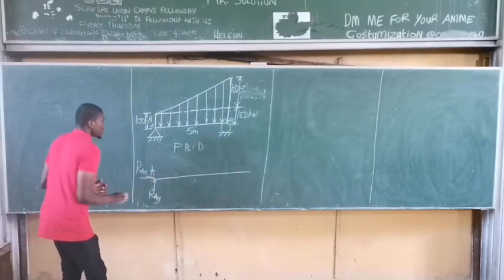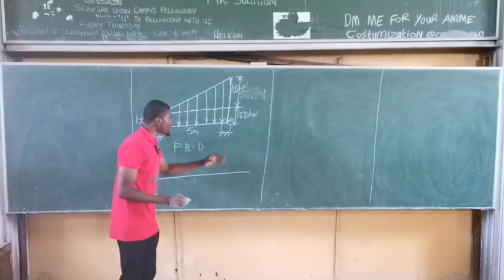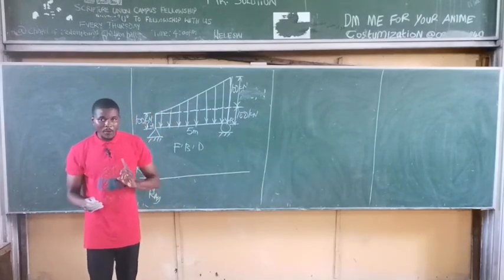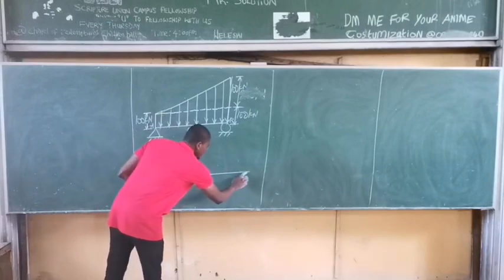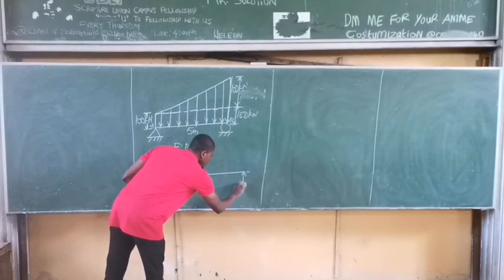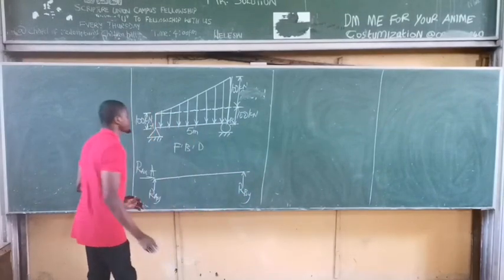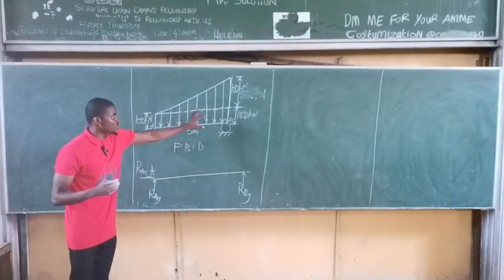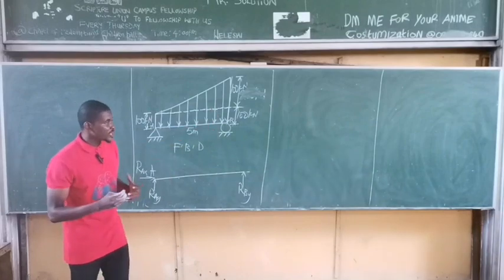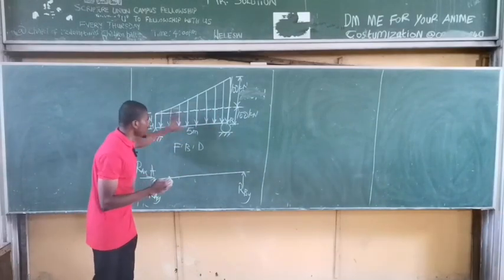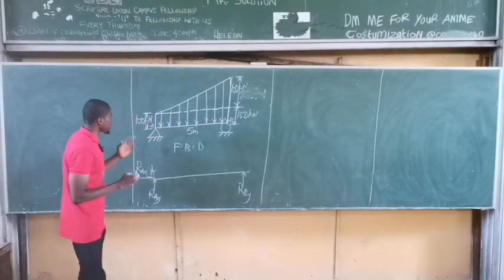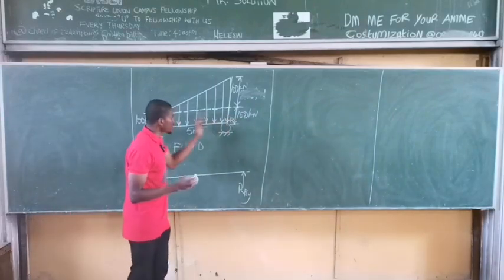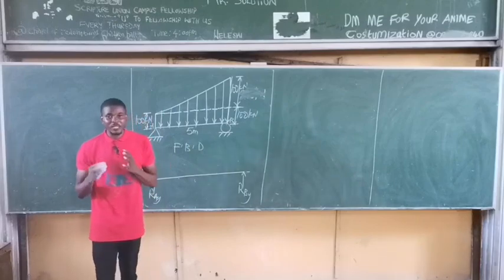This is point A. At point B, we have a roller support, and for a roller support, we have just one reaction, normal to the surface. So you indicate just one reaction, RBY. Now, the problem is how do we then convert this UDL and this UVL? Okay, so let's first of all consider the UDL. The UDL load has the highest intensity as 100 kilonewtons, as can be seen on both ends, 100 and 100. That's the uniformly distributed loading.